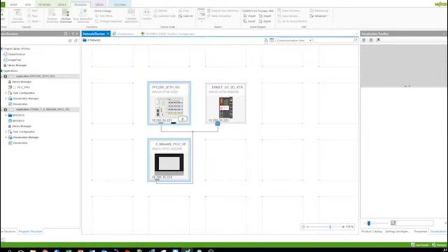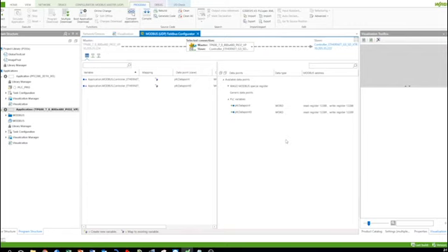In the case of the 750-880, instead of selecting from a list of project variables, I create a list of PLC variables that are mapped to specific %M register locations, and then I map those variables to the Visu panel. If you are familiar with %M registers, then you'll recognize these register locations.